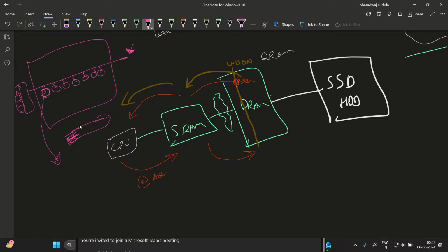This will be clear if you study how the column decoder is designed. It is actually simple, and it takes very little time to switch from one column to the other. It's not like a row decoder. In a row decoder you have NAND, NOR and NOT, some 5 stage gates, and the delay is so high, its logical effort is more and there will be some branching as well.